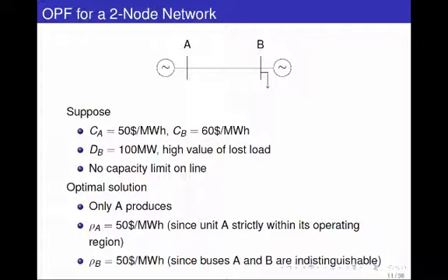And remember, the physical interpretation of this thing is how much power will flow on this line if I ship 1 unit of power from bus B to the hub. And I just told you that A is the hub. Here the topology is quite simple, so you should be able to see what the F is.